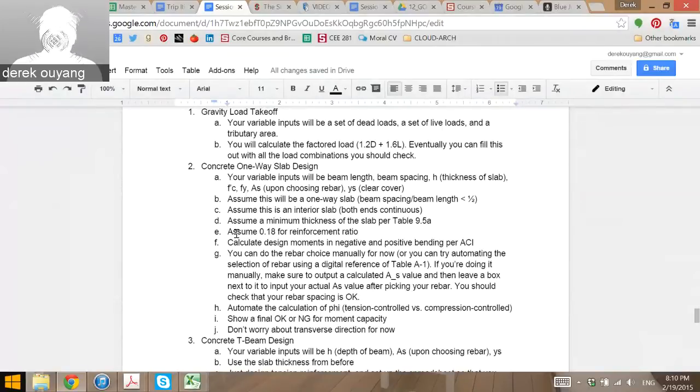Of course, what you can do from here is do a girder design. And the one difference, by the way, when the other input, WE goes into what? WU L squared over something, right, as your moment demand. I think there's a spreadsheet in your notes where it's just giving you recommended ones. But of course, when you're talking about a beam simply supported with a uniform load, the maximum moment you'll experience is WL squared over 8. Have you guys seen this formula before?